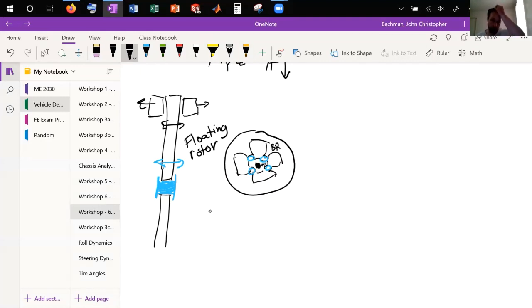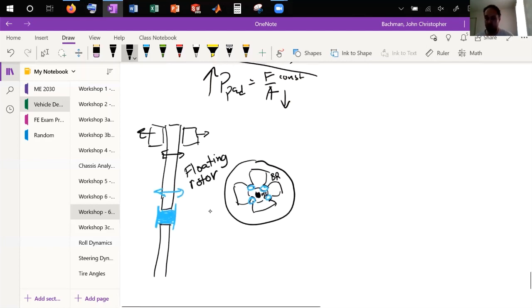Some other tricks: if you're going to weld on the tabs for your brake calipers onto your kingpins, weld them while they're grabbing onto your rotors while they're in place, basically to make sure they're lined up real well, or just have them machined to accuracy, right?